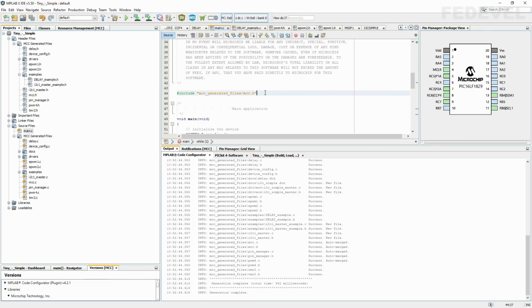Okay, so go into our code, and at the top of our file, up here, write something like this. Define the address of our accelerometer as 0x0E. This line will tell the software that everywhere in our code where we use this word, the software will automatically replace it with this number.